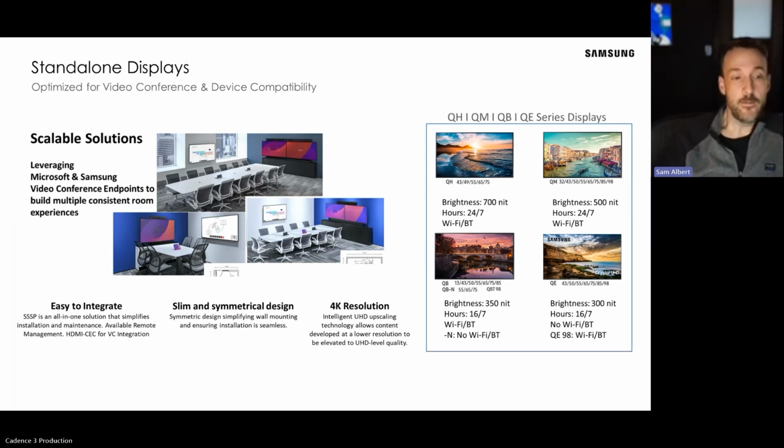That's one factor. The other factor that's also really important is the manageability of those displays. We rely on having our MTRs control when a display wakes and goes to sleep. So all of our displays that we are deploying have wake on sync capability. That relies exclusively on an HDMI signal being sent to the display. If there's a signal being sent, the display will wake up. If the signal goes away when the MTR goes to sleep, the display will put itself to sleep.